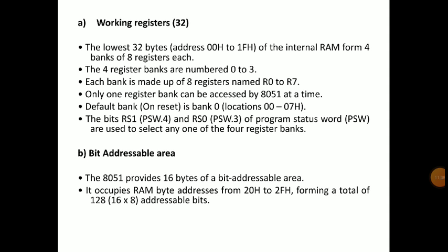The default bank on reset is bank 0, 00 to 07. The bits RS1 and RS0 of the PSW, the program status word register, are used to select any one of the 4 register banks. We have already learnt about these registers, RS1 and RS0, the bank selection bits.